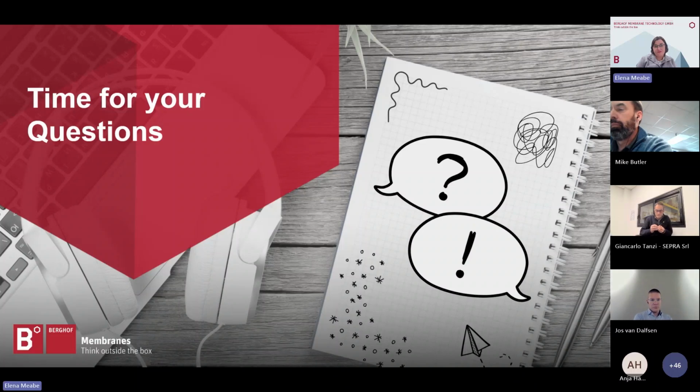Okay, understood. Mike, there is a question about the egg processing wastewater, and they would like to know which recovery you are achieving in this kind of project. If something like 80-90% recovery is common. Do you have this information for the egg processing project? Yeah, so I think 90% is a reasonable target. Perhaps you can go further.